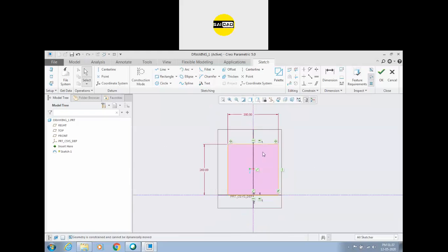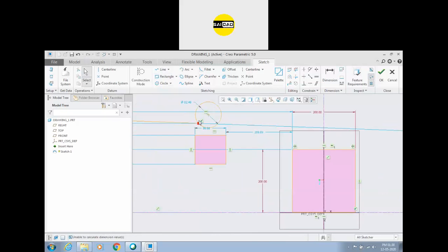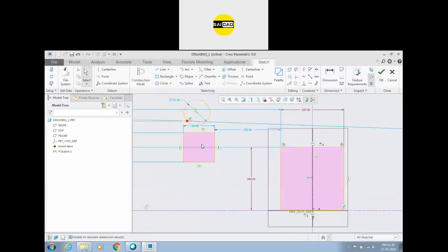So now you can see there is a color. Why is this color showing? Because we have some inspection option enabled. If we create an open sketch, it is an open sketch, not a closed sketch. Closed sketch means a closed body. Okay, a circle or a rectangle is a closed body. But if you have an open sketch, then we will see some red points, and if we have a closed sketch, then we will see this color filled body.